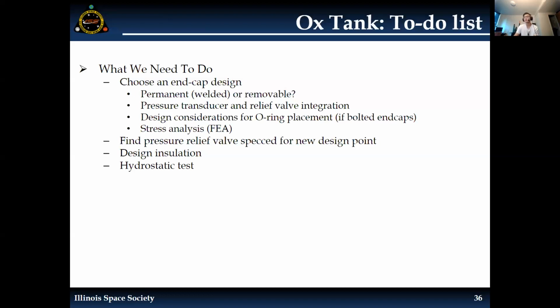Okay, so 2 times the operating pressure, not the... So this is going to be 2 times the storage pressure, not the maximum allowed operating pressure. Does that make sense? So our storage pressure is 45 bar, and our maximum allowed operating pressure is going to be 1.5 times the design pressure. So we're actually going to be pressurizing it to 90 bar. So in theory, it won't break.